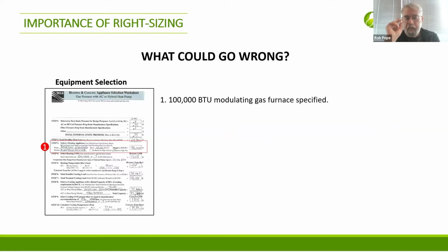So here's the issue. First, the load calculations are done wrong, and that is the foundation for everything else. It is from those load calculations that you then determine your equipment sizing, and then you determine your CFMs or GPMs that you need to deliver the energy to the appropriate places in the house. That is how you size your ducting and piping and everything else. And if your load calculation in the first place is wrong, everything that comes after it will be wrong. And here's an example of how wrong it can go.